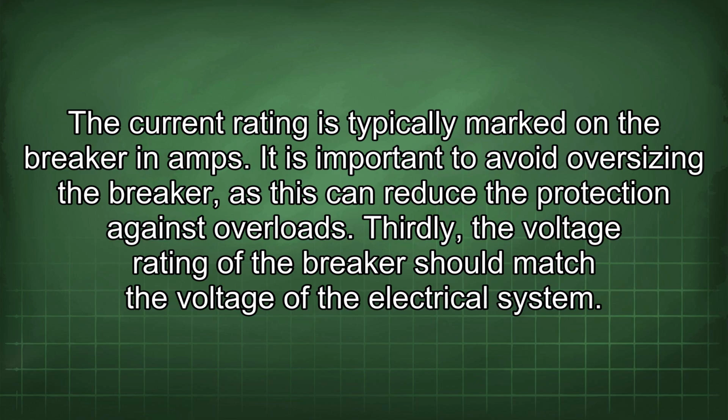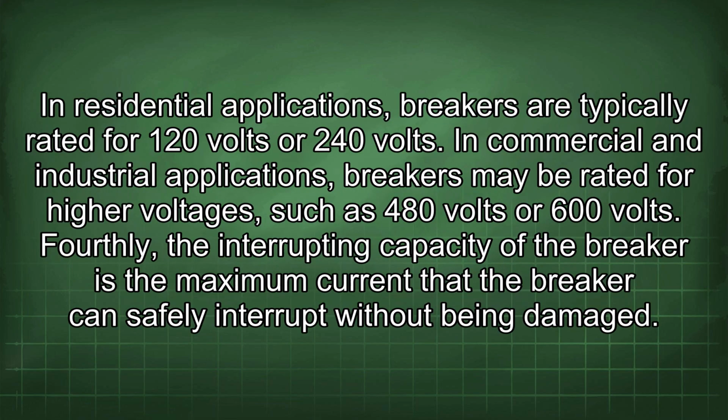Thirdly, the voltage rating of the breaker should match the voltage of the electrical system. In residential applications, breakers are typically rated for 120 volts or 240 volts. In commercial and industrial applications, breakers may be rated for higher voltages such as 480 volts or 600 volts.